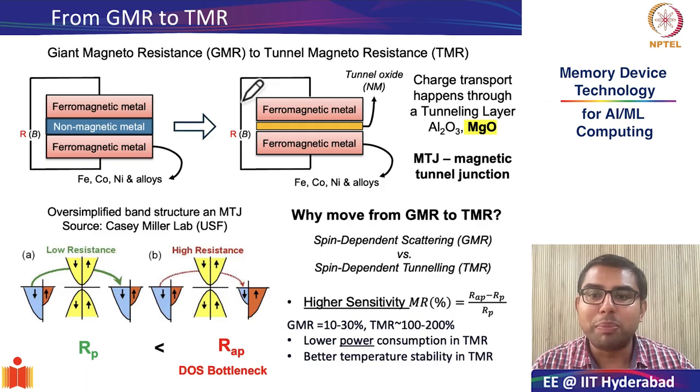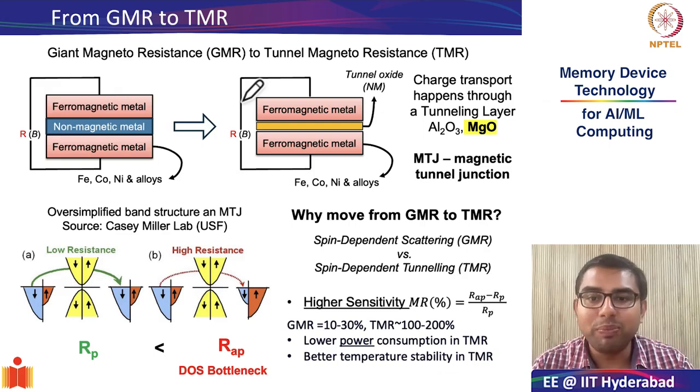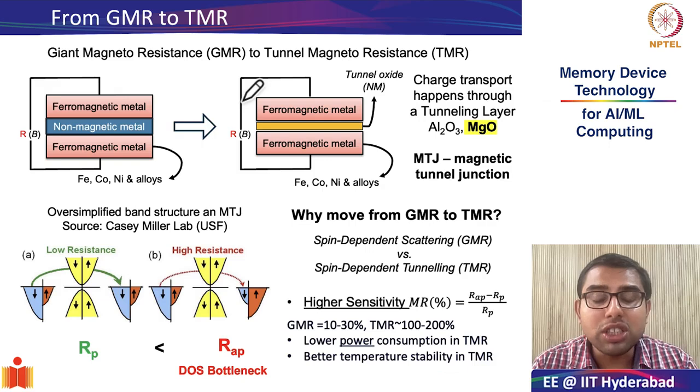So last time we began our study of magnetic RAMs or MRAMs. So let us do a brief recap of what we studied the last time around. First, we introduced the spin degree of freedom, and we saw how spin can be used to store and manipulate information, and that is done by breaking the so-called spin degeneracy through the application of magnetic fields. The key advantage of using spintronic devices was the promise of having low power operation. This is because spin currents are inherently dissipationless.